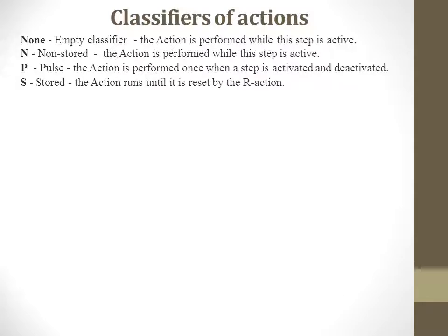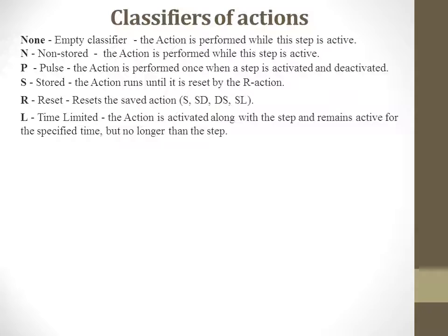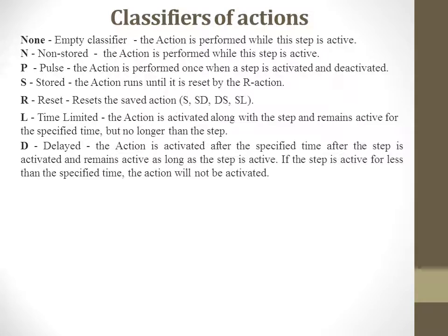S, it means start. The action runs until it's reset by the R action. R, it means reset, resets the stored actions. L, time limited. The action is activated along with the step and remains active for the specified time, but no longer than the step. D, it means delayed.